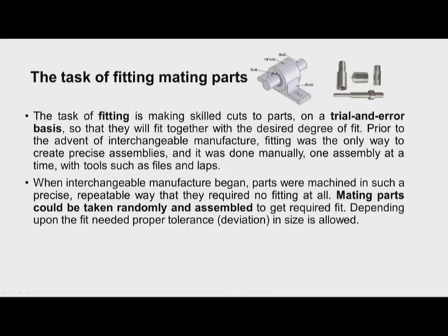So there no motion, no sliding or rotation is required. These two, bush and body, should be held tight, and then here we have a shaft which will be rotating in the bush or it may be sliding in the bush. So there some clearance is required so that it easily runs or it slides. In such cases we should carefully assign the tolerances.